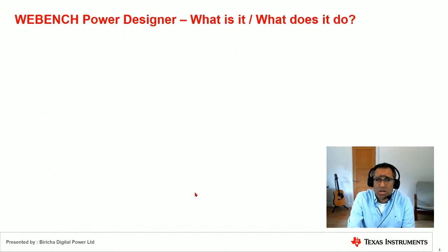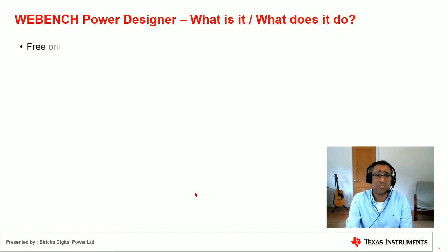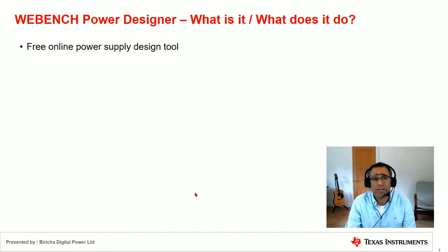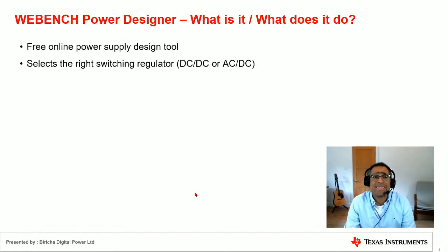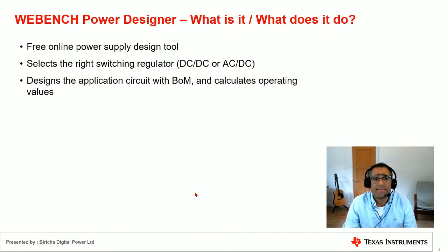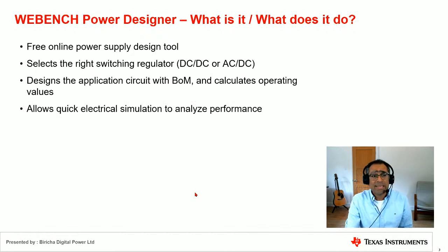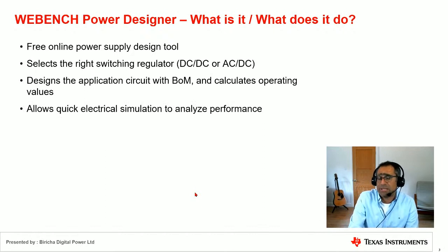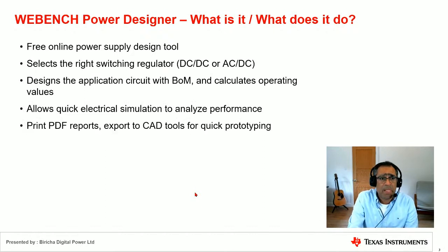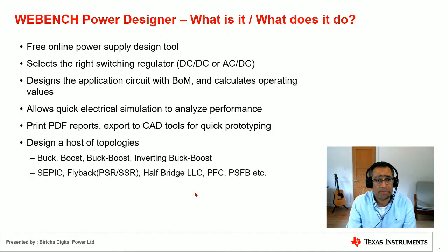So WEBENCH Power Designer, what is it? What does it do? It's a very powerful free online power supply design tool. It selects the right switching regulator, DC-DC or AC-DC, and designs the application circuit with the bill of materials, and it calculates the operating values for you as well. It allows very quick electrical simulation to analyze the performance, and you can get everything exported as a PDF report or even PCB CAD files so that you can do very quick prototyping.